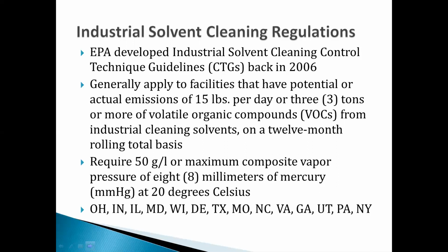But if you are subject to it, the VOC limit is 50 grams per liter, or a maximum composite vapor pressure of 8 millimeters of mercury at 20 degrees Celsius. So 50 grams per liter is, I think, about 3% by weight in general. From our perspective as an industry, that's a very, very low VOC concentration.